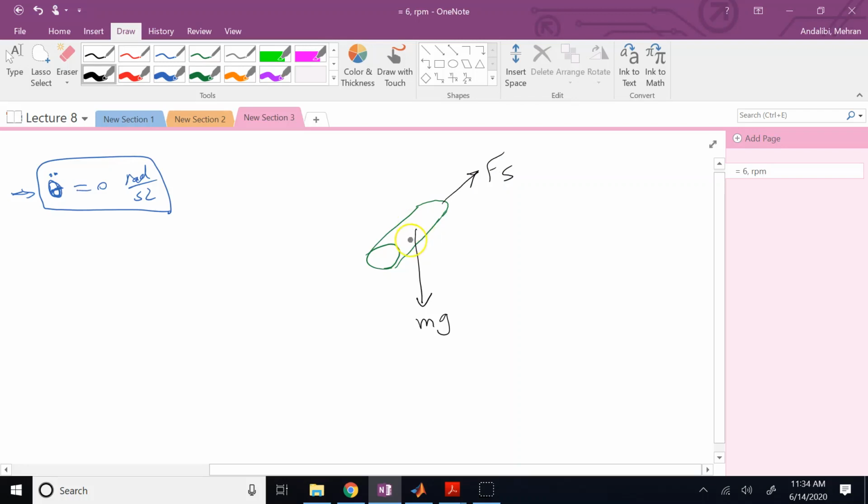Now, the contact we have for the collar and the bar, as we said, there is no friction in that contact, but there is a normal force. Now, which direction is the normal force? Well, in this case, that normal force is in this general direction like this, because the contact is not right at the bottom of the collar. It's not exactly on the right side. It is actually somewhere between bottom and right. So it's somewhere like here. That's where the contact is happening, and normal to it is this N.